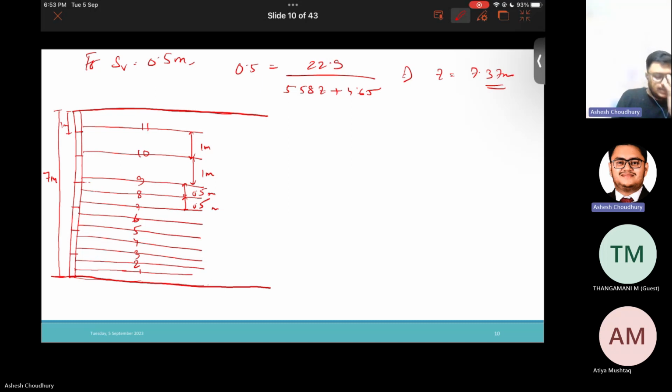And one more thing that is done, to prevent tension eccentricity on each block, small geogrid layers are actually put like this. Small geogrid reinforcement layers are attached here, so that there is no tension eccentricity on the facing block.